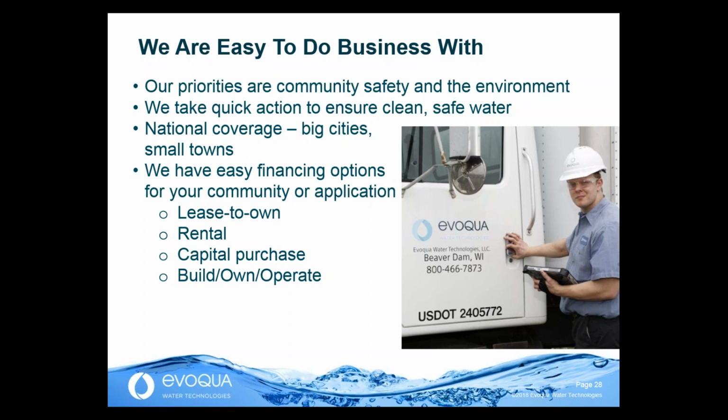The first is, is there something else that the customer wants to remove? For example, are there other organics in the water that GAC could also remove? Or is there, for example, perchlorate in the water that you'd want to look at ion exchange to help remove as well? And then secondly, what could be impeding that performance in the water?